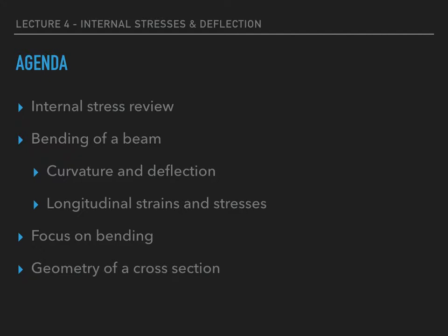Today's agenda, we're going to cover internal stress review, what that means, bending of a beam, curvature and deflection, longitudinal strains and stresses. Hopefully remember those from the first semester. We'll take a close look at bending and then talk about the geometry and its importance.